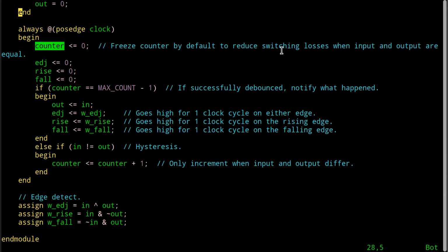And the answer they chose is no. And the value is that what it does, if the counter doesn't go, is not doing anything when it doesn't need to do anything, what you're doing is reducing the switching power consumption. So the losses that they're talking about here is in wasted energy and potentially EMF noise and stuff inside the FPGA. Why let all these gates and stuff chatter if they don't need to? This is a good idea, in my opinion.